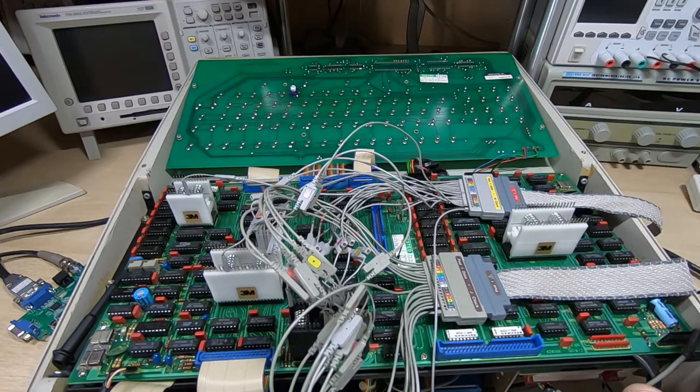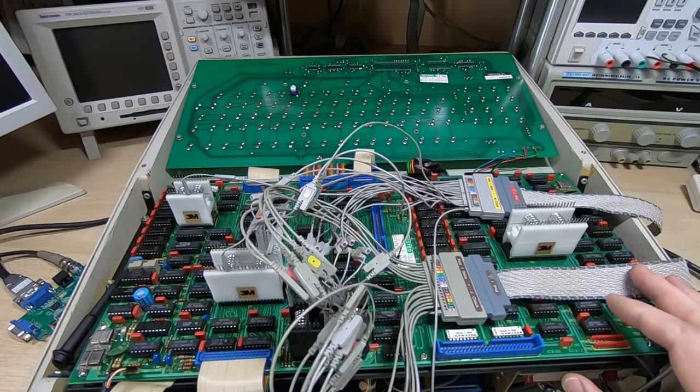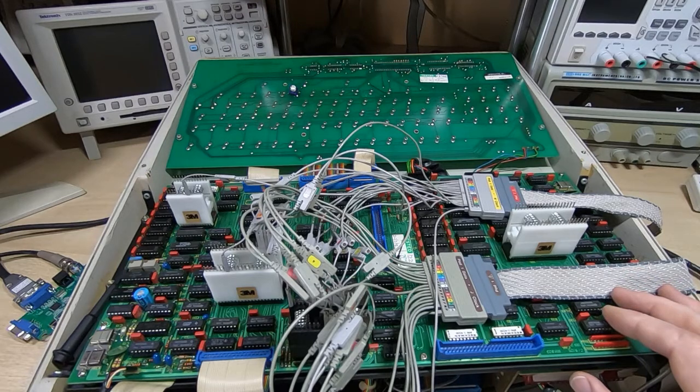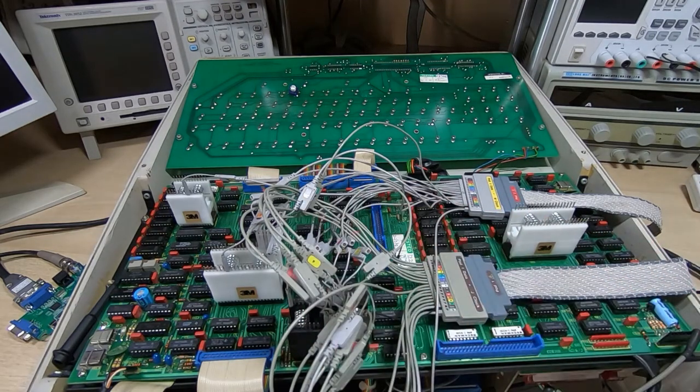Now, as you probably know, it's not quite as straightforward with floppy disks as just having the data on the disk. It needs to be in a certain format. The information in the disk headers needs to be correct. It needs to match the disk, and it also needs to match the drive that you're putting the disk into. And then the measurement circuitry should be able to lock on to the disk speed and start reading the raw data from the disk and turn that back into the stored data.